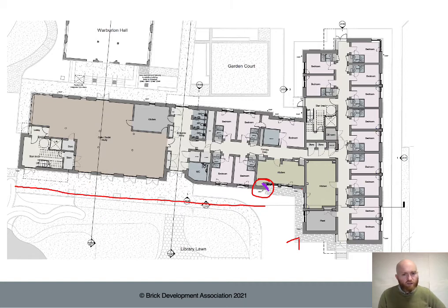And then moving to this long section of brickwork here, clearly all of that together looks like it's going to be longer than 12 meters, but actually we've got a bit of a recess here for the opening. So actually check the elevation, see does that recess run the full height? In which case maybe we can use that as a natural break in the brickwork to introduce some movement joints. So the first thing would be to determine whether this section here, if that is the case, is within 6 meters.